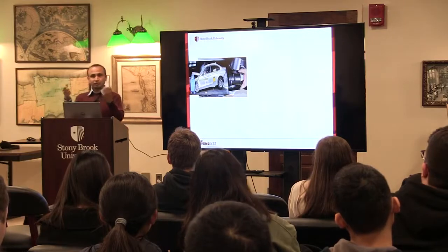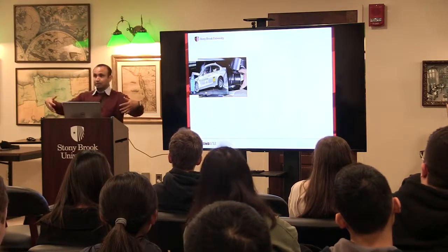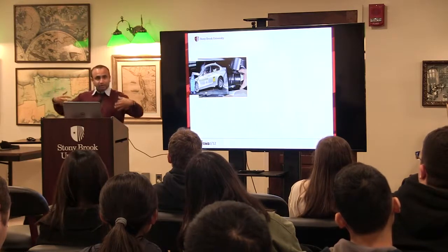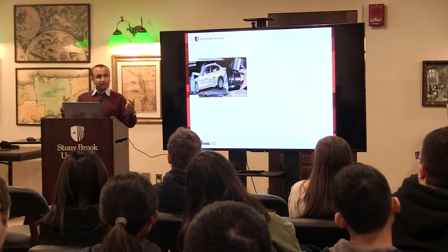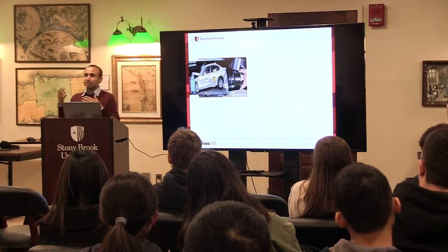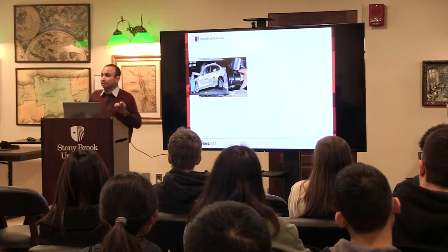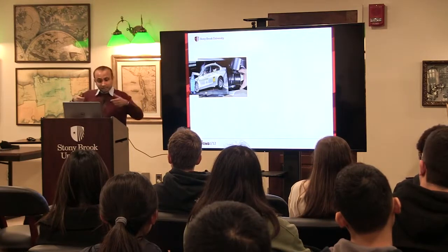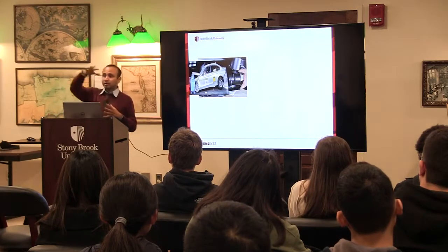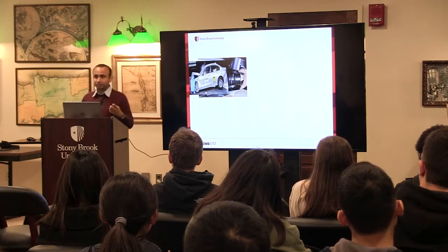Imagine if you're driving a car, it has a front bumper, and a lot of times today even that bumper is made from composite. Behind that bumper, there are these cans which are shaped like a soda can. It's cylindrical in shape. And the function of the bumper and then the can is to basically absorb and dissipate the energy of the car. Anytime there is an accident, when it is, let's say, very low velocity, the bumper is what absorbs that energy. For mid velocity, it is this crush can which absorbs energy. And then for high velocity, the entire frame of the car will absorb energy.